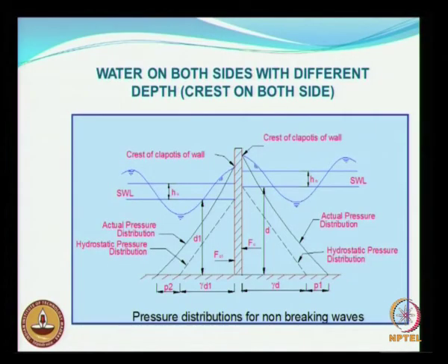So water on both sides with different depths, the condition will be crest on this side, so maybe you have a higher water depth, and then the water depth on this side is less than this, so you have a differential water depth and differential pressures and forces acting on the wall. These conditions may be a bit rare, but still you need to consider them when you face such a situation.